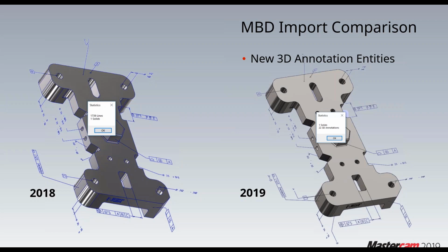Anytime you have a CAD system, it's trying to track every single entity in 3D space all the time. So if any of you have gotten a part that has 1 million solid bodies or a ton of wireframe, the system can slow down because it's trying to track all those entities in real time. If you try to rotate the part or change views, it can really slow things down. So for a very involved part with a lot of annotations, this can really speed things up.